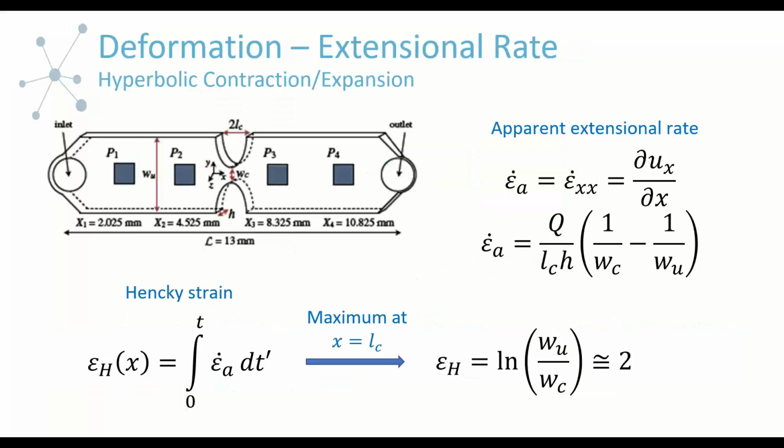Okay, so just so that we can see how we are actually going to calculate these components, the extensional rate and the normal stress, to get our extensional viscosity, we're going to take a closer look at our flow channel. I've already mentioned the microfluidic nature of our channel, but to remind everyone about our technology in general, it's the combination of the microfluidics with the MEMS. So we have the pressure sensors spaced along the lower or the base of the flow channel.